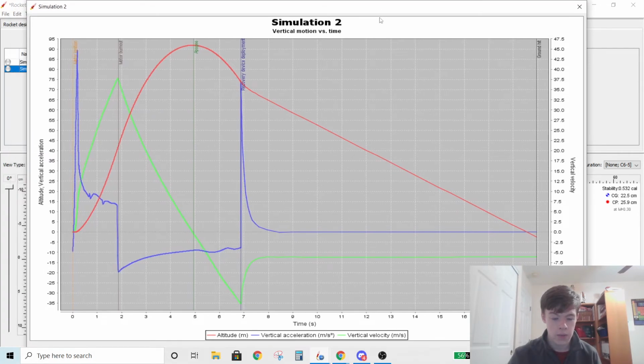The important things here, you look at your acceleration. Hey, this looks familiar. It's almost like it's the thrust curve of our motors. Shocking. Next, you'll see velocity, and it follows that same kind of accelerating, and then it has a little acceleration, but it keeps going solidly, and then it stops accelerating, and then it's gradually decreasing. It slows down the decrease rate because of drag slowing down, which you can also see in the negative acceleration lowering. Right here, it hits apogee, which is shown.